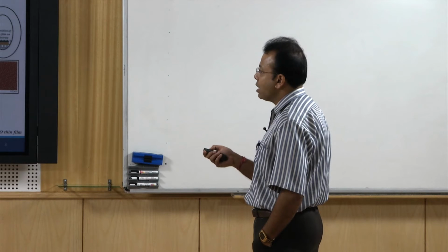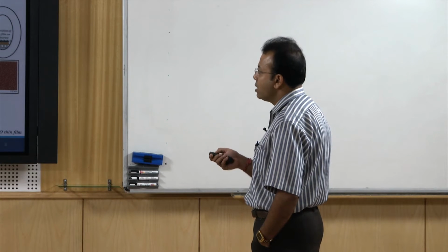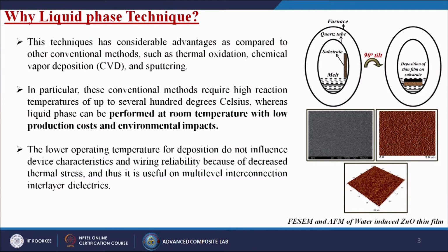These techniques have considerable advantages compared to other conventional methods such as thermal oxidation, chemical vapor deposition and sputtering techniques. In particular, these conventional methods require high reaction temperatures of up to several hundred degrees Celsius, whereas liquid phase can be performed at room temperature with low production costs and low environmental impact.